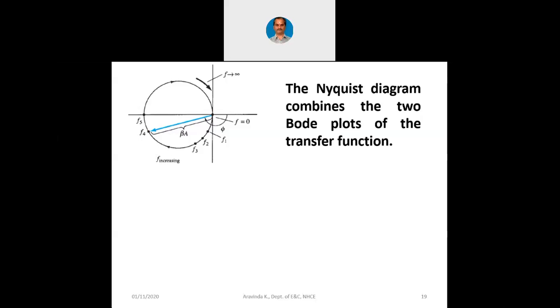Now don't get confused by the frequency response curve of Bode. In the Bode plot at the mid frequency, we have stable gain and stable phase shift also. But Nyquist indicates in a complex plane that with the increase in frequency, magnitude will change and phase will also change.